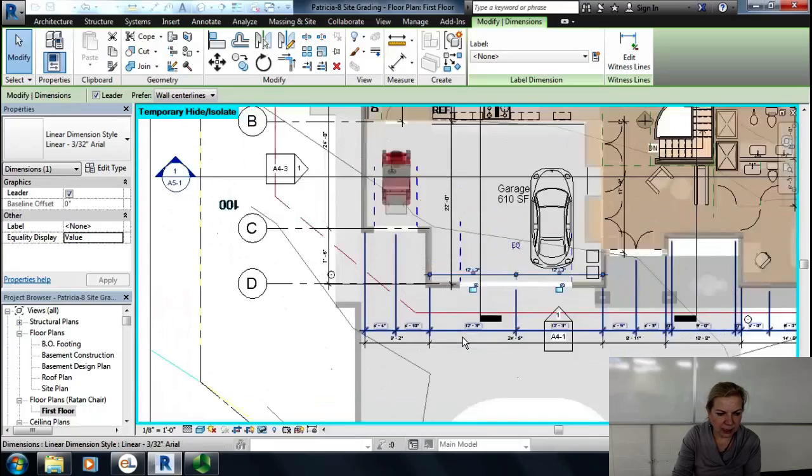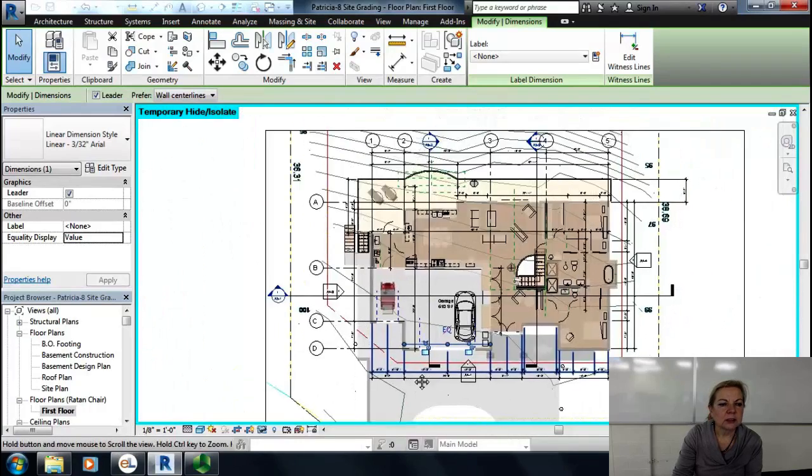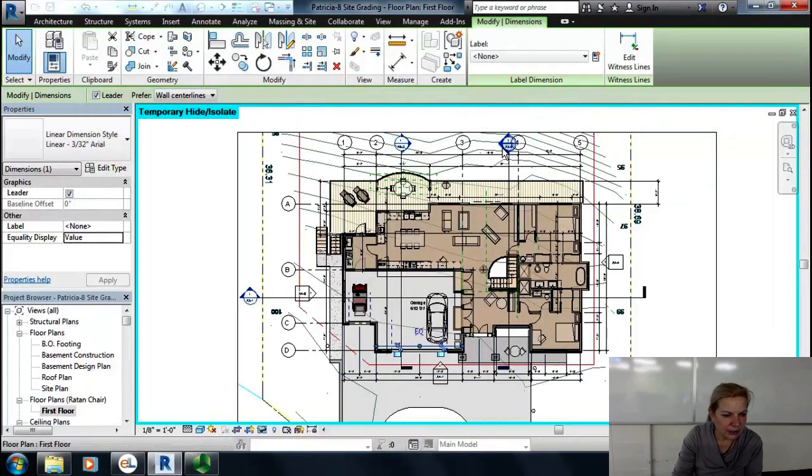But let's now finish the content of our presentation with actually something that you need to know before you even start dimensions. I placed grid line, but most of you don't have grid line. I placed grid line first. What your drawing should have is overall dimension, and your grid is usually top and left. Your overall dimension should be at the top and on the left or right. And I have jogs in my house, and most of you also have jogs.